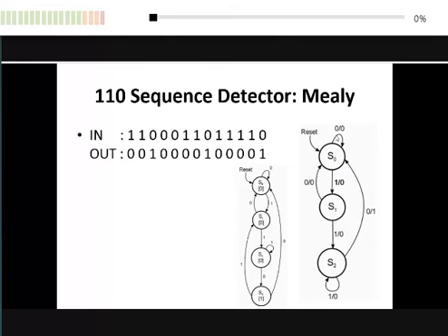Okay. This also means your input sequence is complete. You start from S0, your input arc is 0, 1, 1, 0. So that means while you transit from S2 to S0, your output is completed. That's why we label it 1.